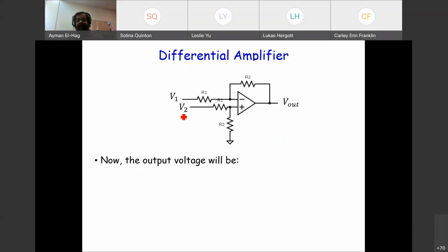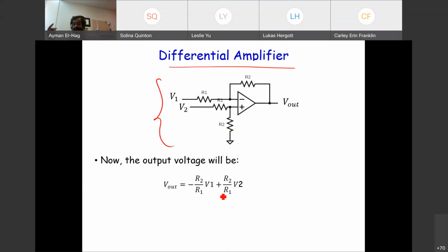So this is the final design. This is the differential amplifier. It's basically an op amp, but it will have two resistors. This is the inverting amplifier, nothing different than the circuit I mentioned at the beginning of my class today. However, I will add another circuit, which is R1 in series with R2, so that we will get our output. Now this becomes R2 over R1 as we intend to have, and this is my differential amplifier, R2 over R1 times V2 minus V1.